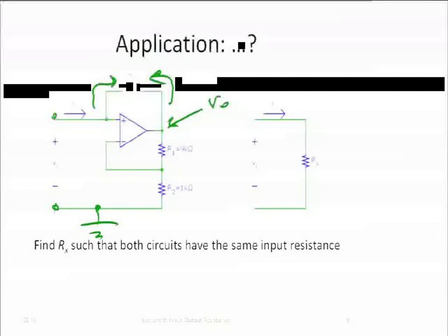Yes? So you said VI is independent of II, right? So they're not dependent on each other. But if you write a KVL for the whole amplifier, so you start at V out, and then you go through RF, and then you come back to VI, then that means that your V out is dependent on RF. Does that make sense?